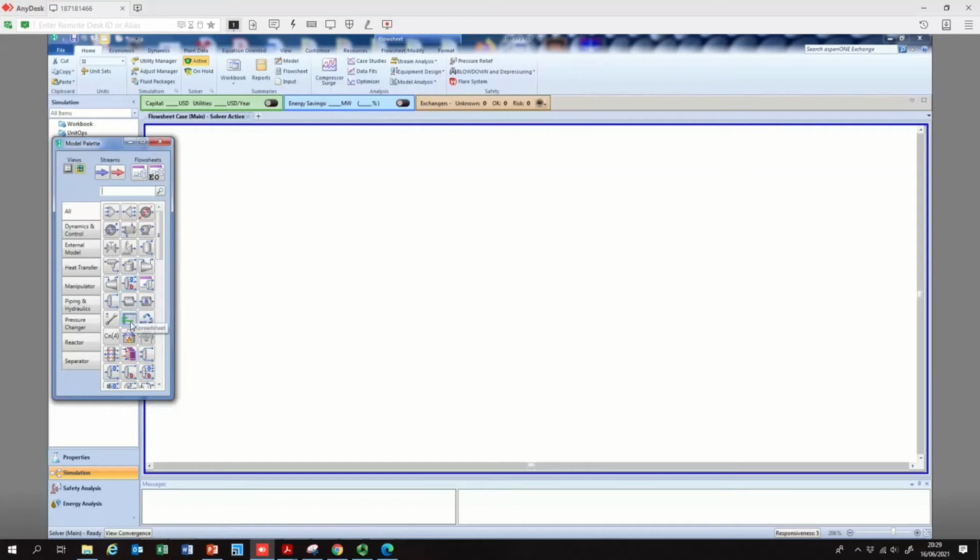This is something like Microsoft Excel. And then you can add formulas like something we do in Microsoft Excel. And I don't know if you know how to use a solver add-in in Microsoft Excel. If you know that, we can do something similar in Aspen HYSYS using this spreadsheet followed by the adjust function. But anyway, I will show you how to do this.